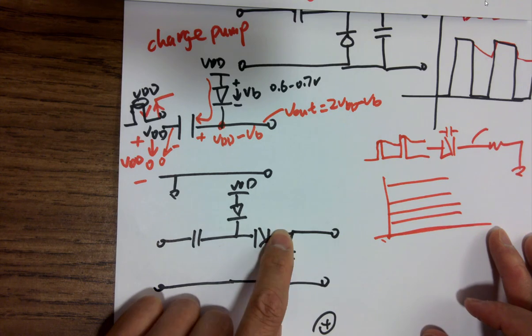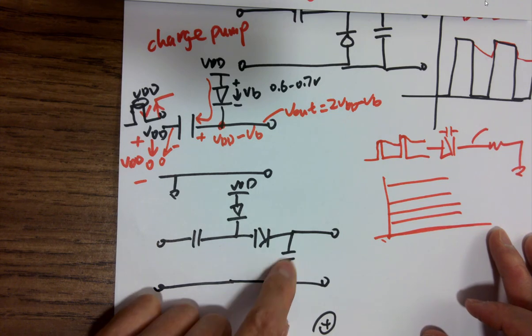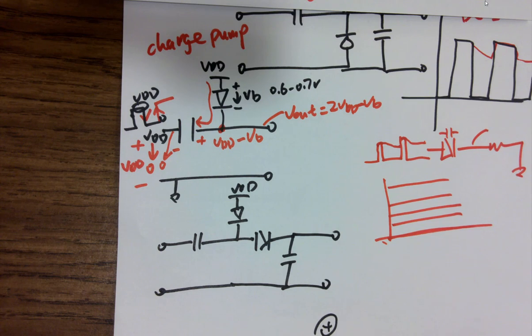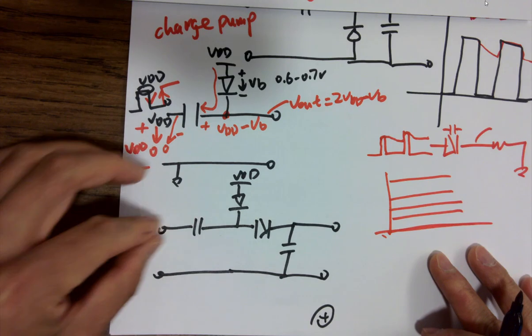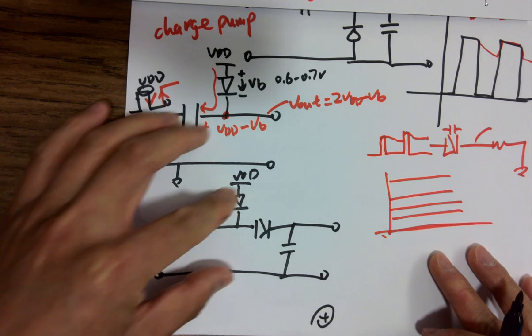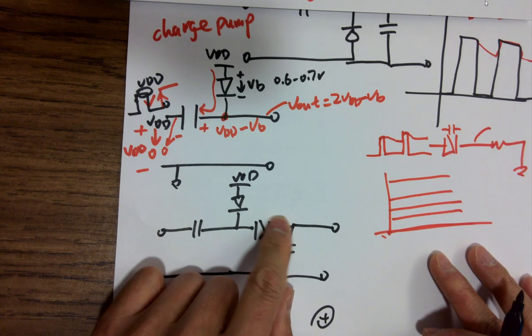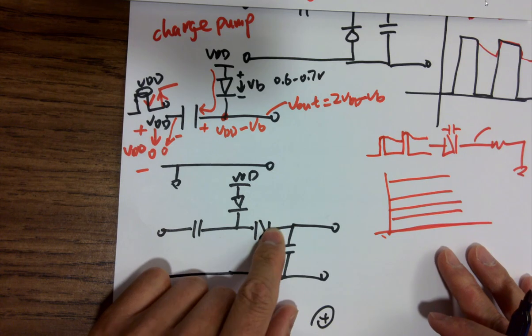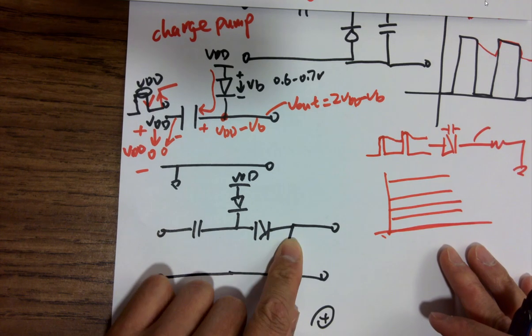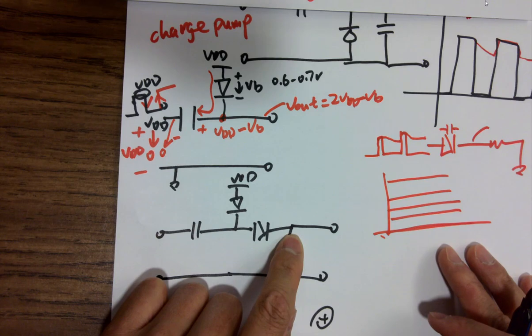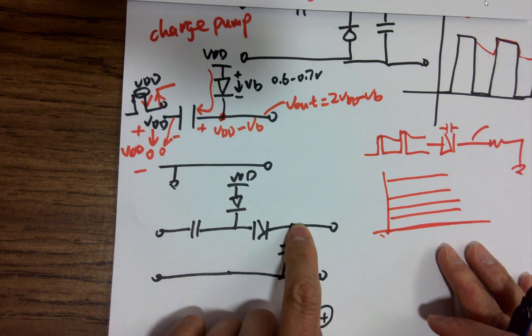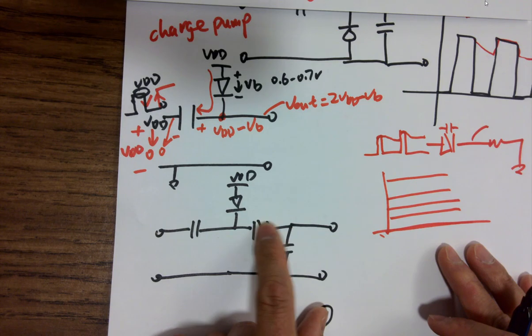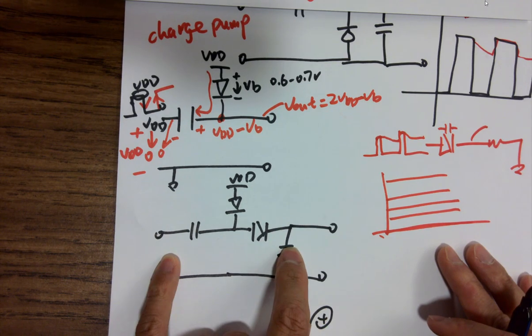And what is this circuit? Remember? It's a charge pump. This is a charge pump. That's a voltage doubler, right? Yeah, a charge pump or voltage doubler over here. But this guy is just a rectifier type of low pass filter, and we add a diode over here just to prevent the charges from going backwards. The capacitor here will serve as a low pass filter.